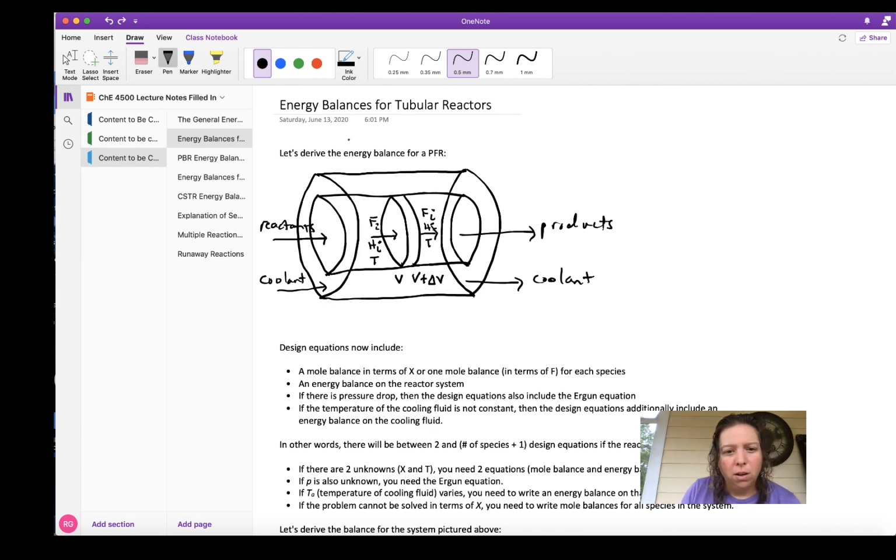There's one more thing I need to account for in this countercurrent case, and that's that I know the temperature coming in here. This value is specified. I know what temperature the cooling fluid enters the shell. I don't know the temperature here. When I'm doing these energy balances, I usually know the inlet temperature, not the outlet temperature.